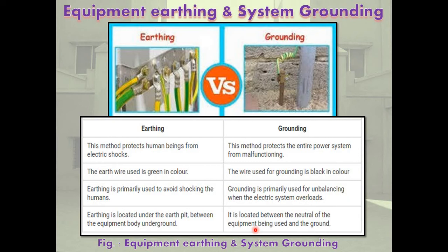The neutral points are available from the star connected generator, star connected transformer, and star connected stator windings of motors. The earth is a good conductor. Earthing mass is a metallic fabricated mass of steel rods buried and placed horizontally in the ground. The neutral points to be earthed are connected solidly to the earth by means of a continuous conductor of low resistance, less than 0.1 ohm.